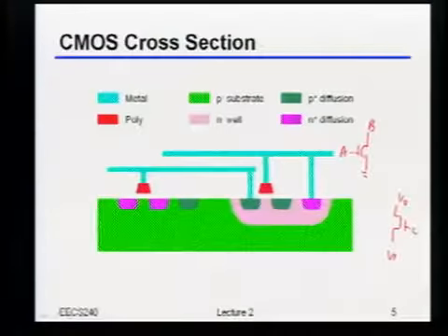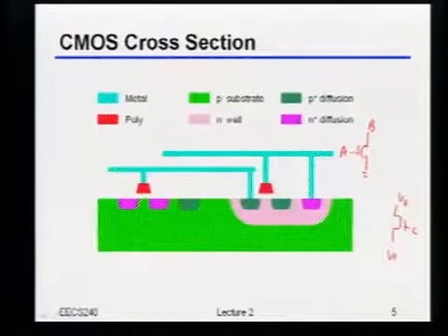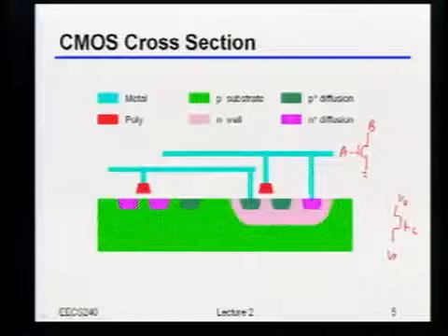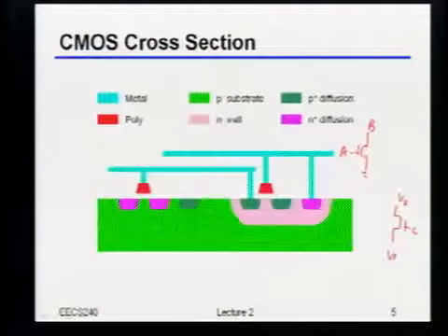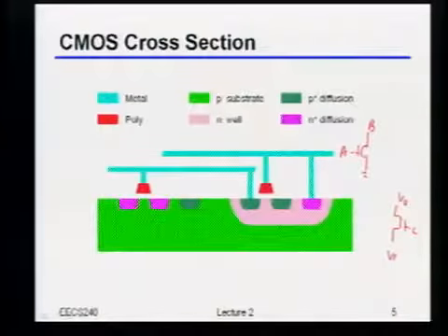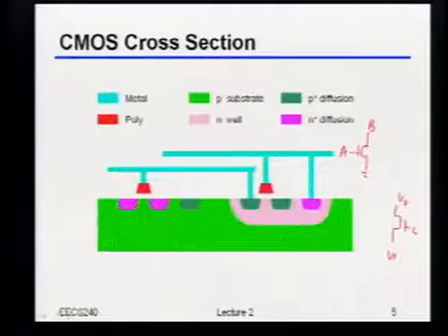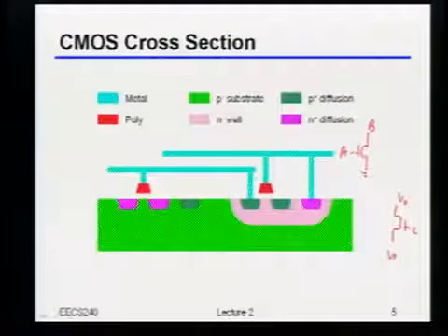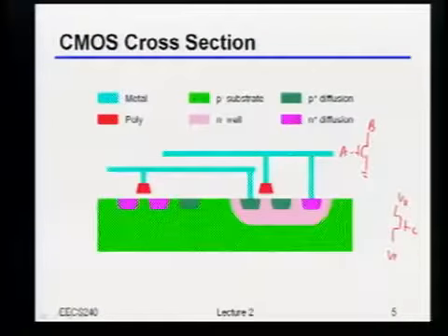So I'll call these A, B, C. So these are all just the nodes that I've labeled there, okay? So I go and I type this into SPICE, and I try and simulate that circuit. So in SPICE, assuming A, B, C, and VI and VO are all sort of independent of each other, is there somehow any connection between those two transistors, or are they totally independent of each other? Again, in SPICE. What do you guys think?